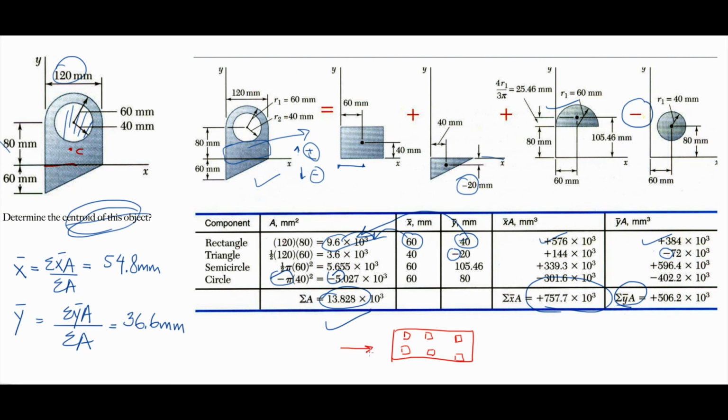If we have an earthquake force that's applied to a story, we need to calculate the stiffness of each element and then convert or move the whole system into a point here that we call center of rigidity. And to do that, we will use first moment of area, which is the one that we just saw. And why do we do that? We need to know what's the opposing force, F, let's call it, that we need to calculate, or we need to design for taking the force of the seismic.